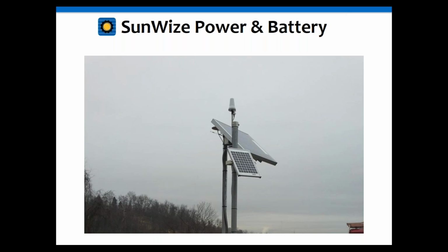The other thing you'll notice is that the solar module in the background is being shaded by the pole from the solar module in the front. Even though you might be thinking, oh, it's just a little line, it's not a big deal, it is. It actually takes out the entire solar module so that it no longer functions. We will talk about that more when we talk about shading in a minute.